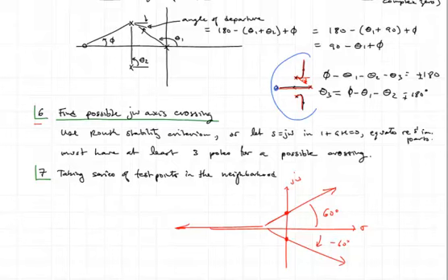And once you have that drawn, you can then think about how you want to modify the root locus by adding some further zeros or poles in your compensator. Or if you can work with that particular root locus plot, then you need to decide where you want to place your actual closed loop poles on that locus of points. And then to achieve that, you have to pick the proper value of k. So this is the big picture, and in the next lesson we'll work through these steps on how to construct the root locus plot.